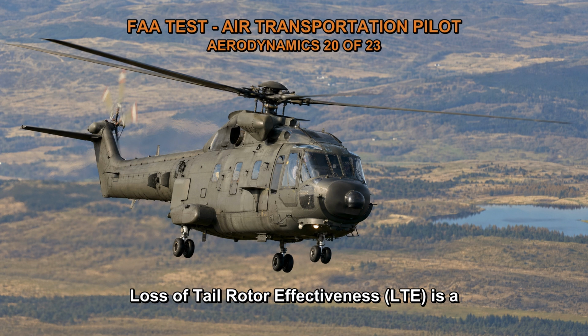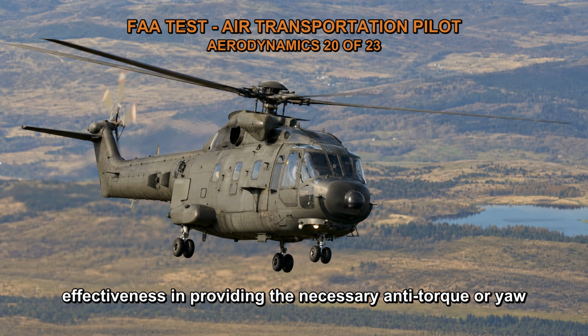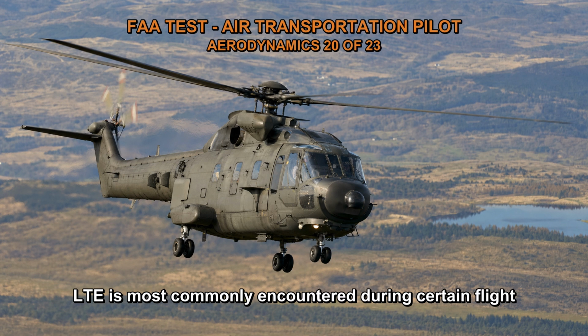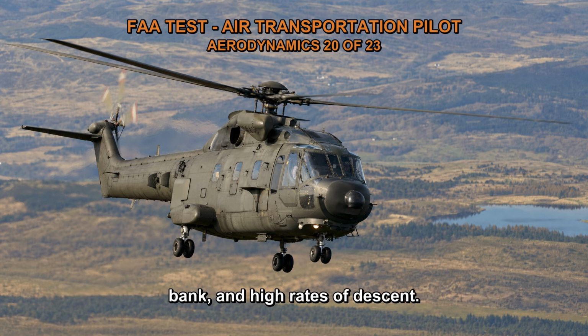Loss of tail rotor effectiveness, LTE, is a phenomenon that occurs when the flow of air through a tail rotor is disrupted or altered, leading to a loss of the tail rotor's effectiveness in providing the necessary anti-torque or yaw control for the helicopter. LTE is most commonly encountered during certain flight conditions, such as high power demands, high angles of bank, and high rates of descent.